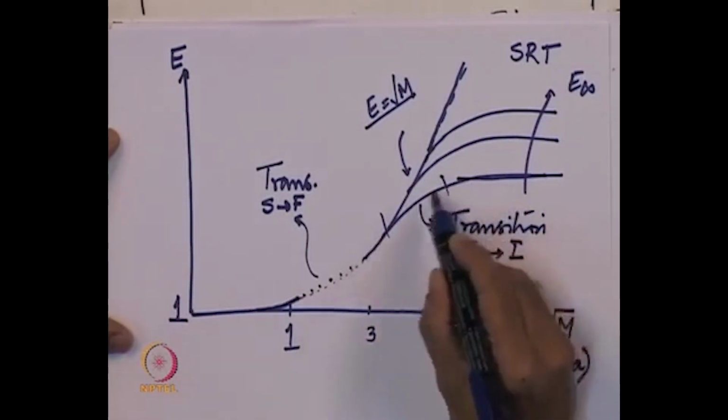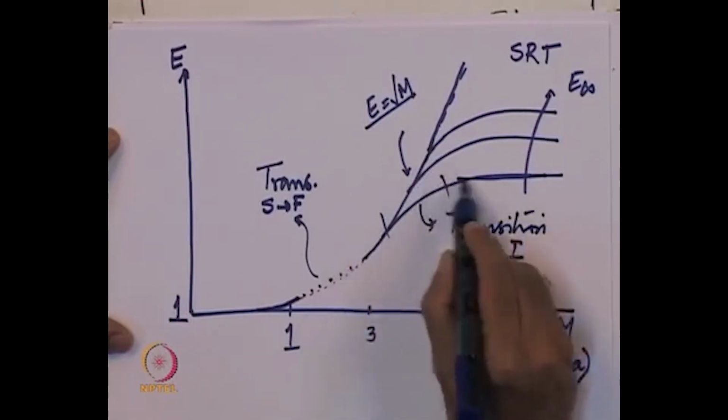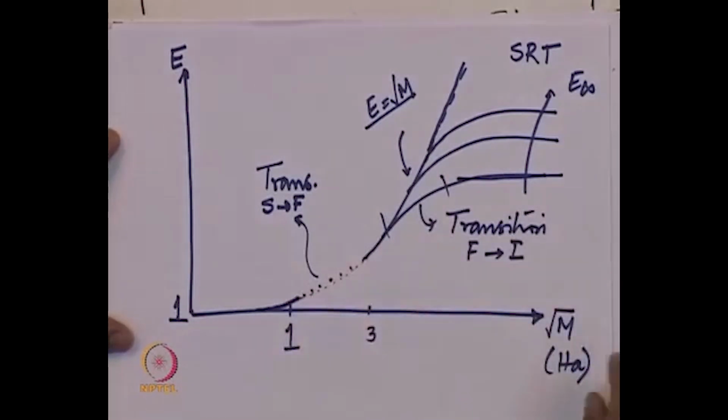One can of course graphically do an interpolation between this asymptote and the appropriate asymptote here, but it has been shown that a good approximation is to use the same expression that we derived with the film theory, making a pseudo first order rate assumption, except that the pseudo first order rate constant is calculated as k C b I, using the value of the concentration of B at the interface, rather than as k C b B, which uses the concentration of B in the bulk.